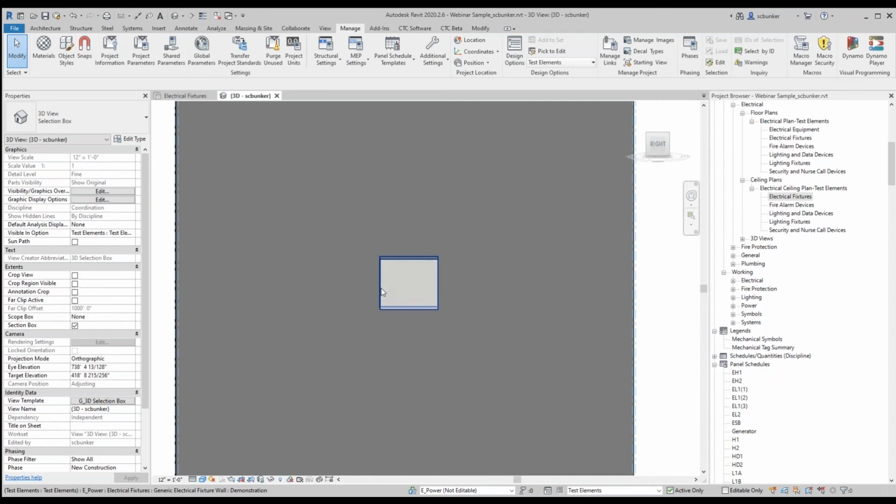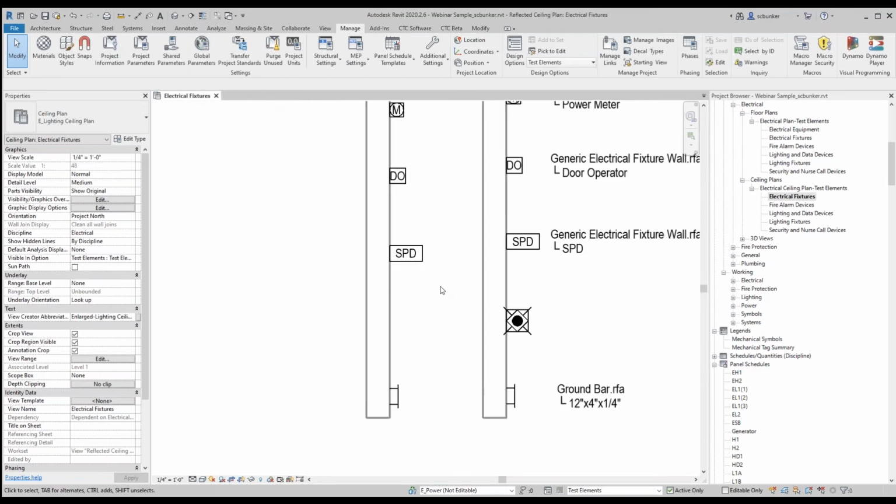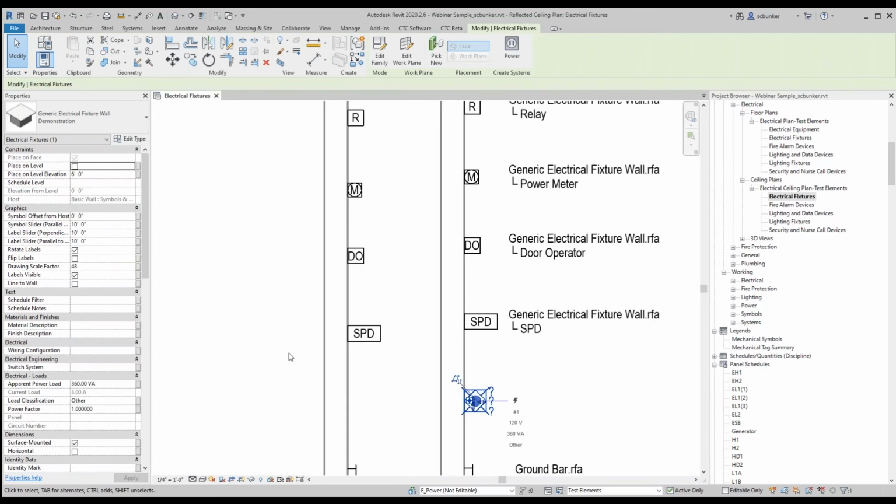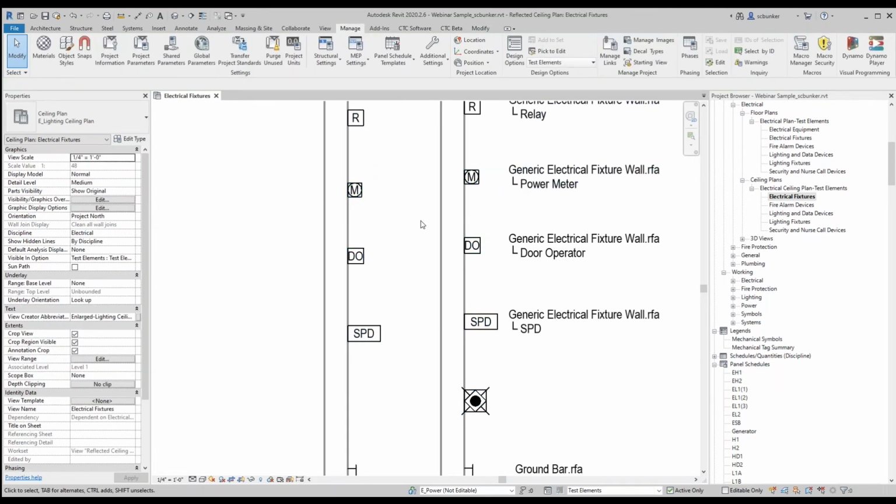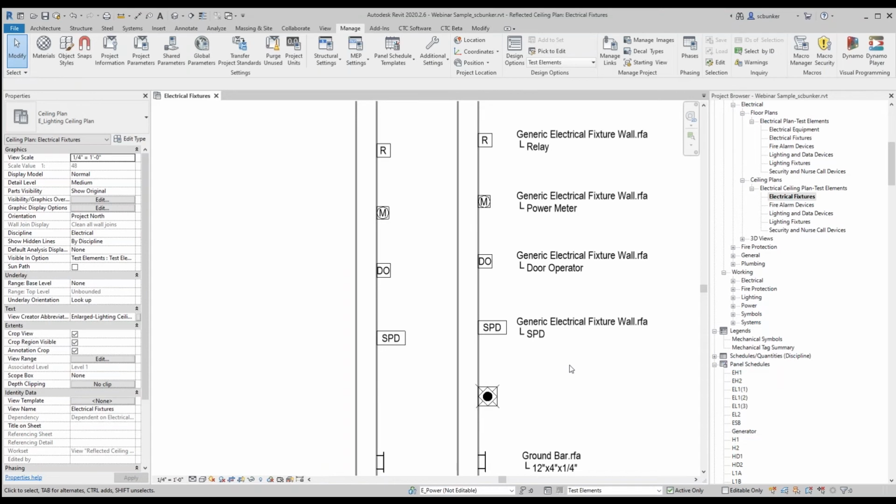And a lot of times the electrician just installs the box and then some low voltage contractor comes in later and pulls the cable and puts the faceplate on. So the only thing that really matters for us is what does it look like on plan? And so with all of these options, you can control the size and shape of the box and whether it's horizontal, vertical, or surface or recessed for the actual 3D model, but all the options are the symbol. So like I said, all these symbols are the same, even though they look different. And one follow-up question that commonly comes in around this also is, of course, all of these items can be tagged using traditional Revit tagging methodology. Yes, certainly.